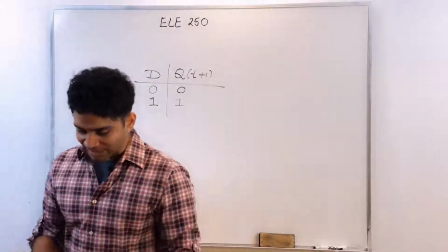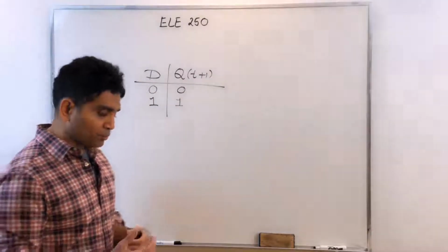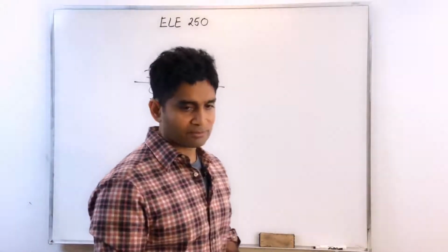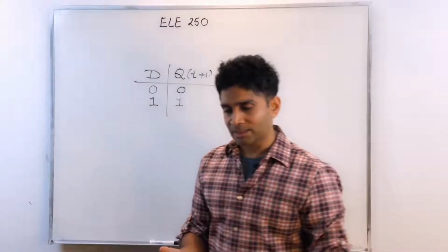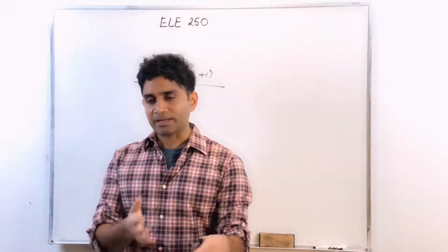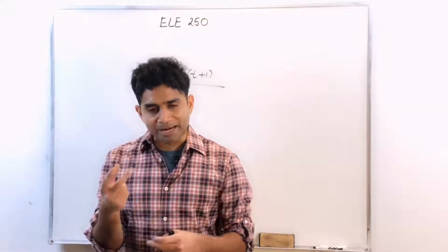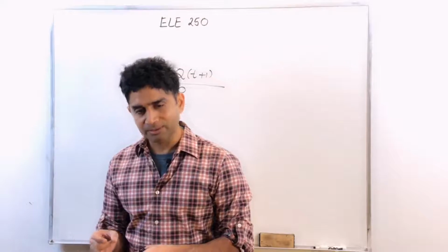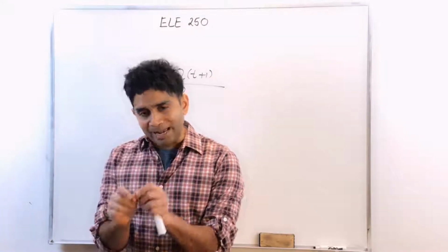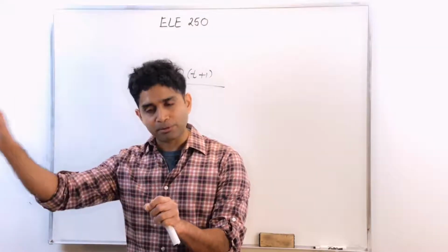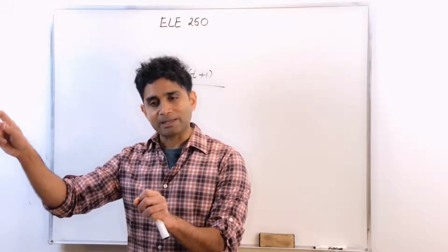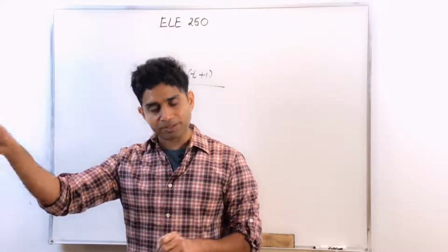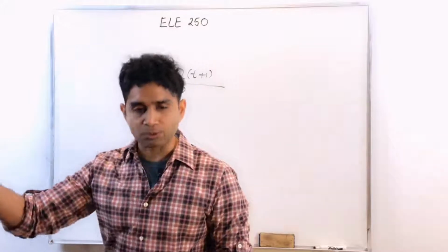And in the last class, we also looked at the scheme to produce addressing. If I have 4 registers, then I can have a 2-bit address, a unique address for each register. When I apply that address, I'm selecting that particular register, and then I enable the load enable signal on that register, and the data is stored in it.